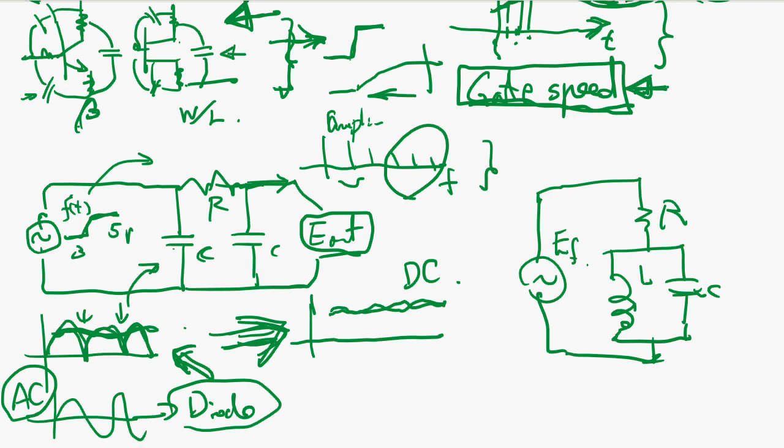So impedance here is going to be pretty low, some peak, and like that. Okay, so using this peak, detecting this peak frequency, and knowing this C, we can measure L.